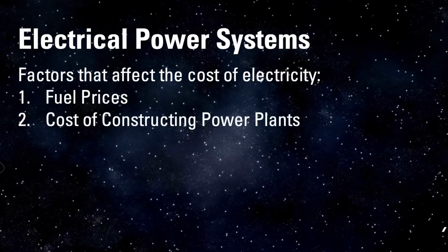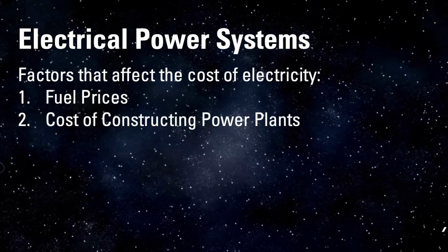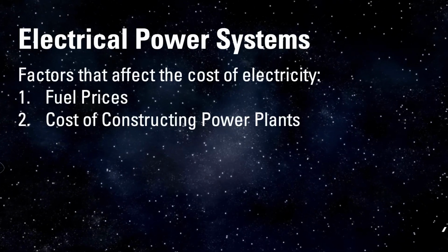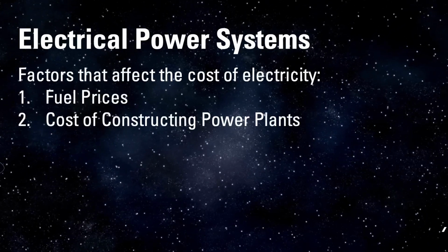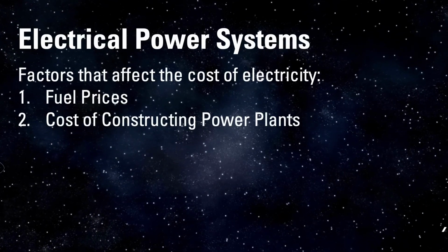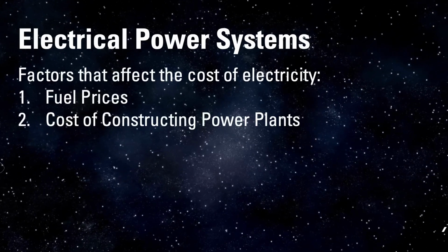It represents the average revenue per unit of electricity generated required to cover the costs of building and operating a generating plant during an assumed financial life and duty cycle. It can be computed by dividing the total life cost of a power plant by its total lifetime energy production.